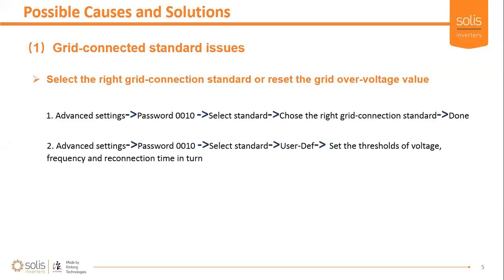For advanced settings, we should enter the password, then select the particular standard as per the local grid available in that area, or consider help from our service line executive. We can also set the threshold value of the voltage, frequency, and the reconnection time.